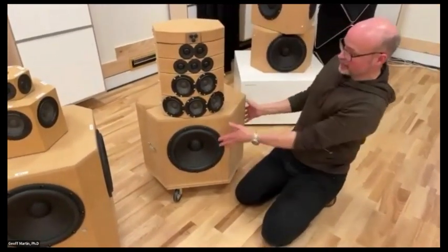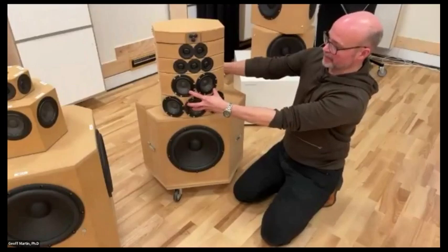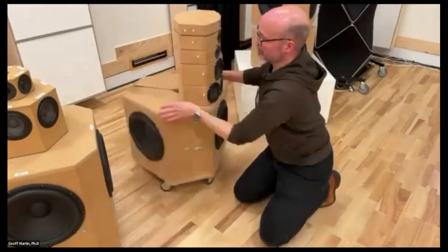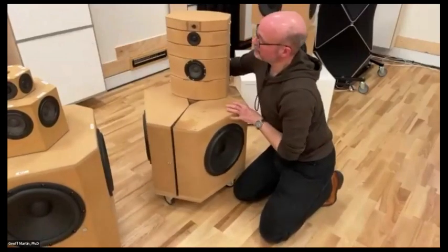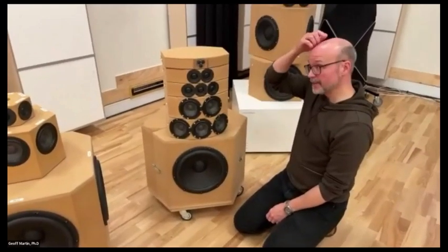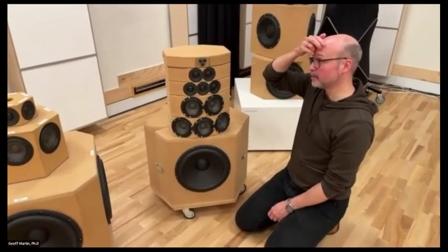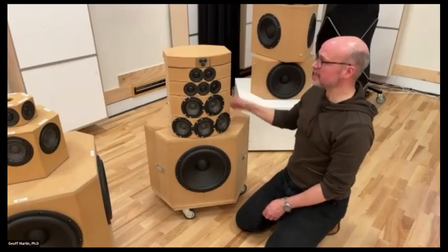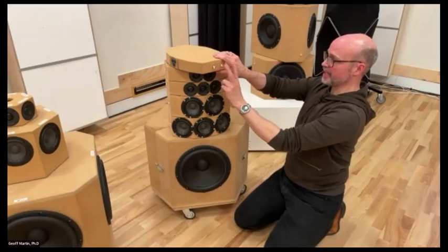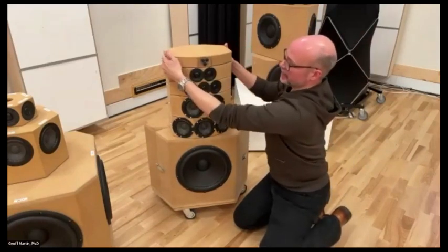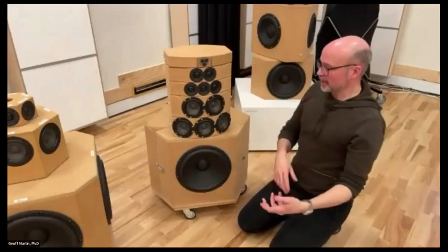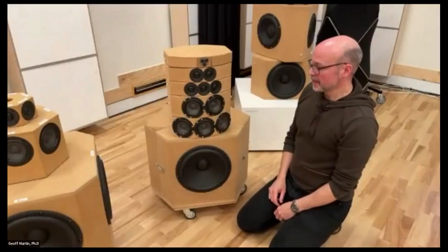So what we had here was 3 woofers, 5 + 1 mid-ranges, so 6 of those, 6 tweeters, there's a tweeter in the back as well, and then 4 of those 8mm dome tweeters to look after the very top end from 10, 15K up to about 40 kilohertz. And as I said, every one of these is connected to its own independent amplifier channel and DSP channel. These all get measured in our pseudo-anechoic chamber and then brought into a listening room to have a listen.